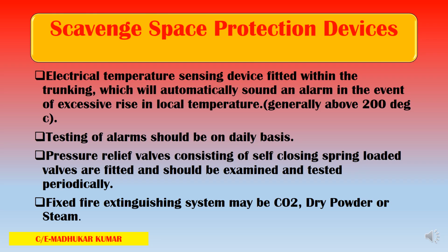Testing of alarms should be done on a daily basis if possible. Otherwise, whenever you get an opportunity within a week when the engine is running, or as per the voyage to voyage basis. Pressure relief valves, which are self closing spring loaded valves, are also fitted. They must be examined and tested as per the engine manufacturer's requirement. Basically, the excessive pressure generated in the scavenge space is relieved by these.